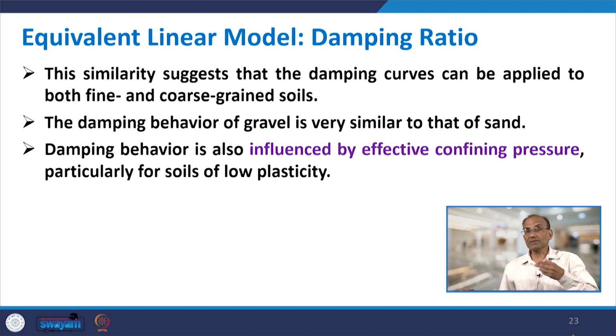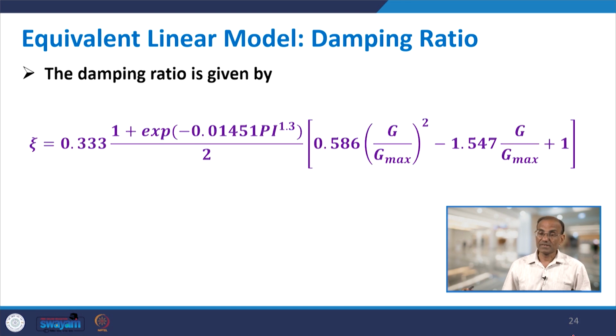But they could be similar to sands, and the damping behavior is also influenced by effective confining pressure, particularly for soils of low plasticity. If you have soils of low plasticity, then the damping will also be influenced by effective confining pressure.